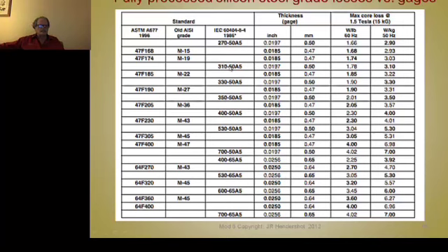The IEC is a European standard, and they don't have exact equivalent grades to the American standard grades. Their half a millimeter lamination is 0.0197 inches. Our half millimeter lamination is close, but a little off, so there's a slight difference in core loss. This is thicker, so the core loss is a little higher.